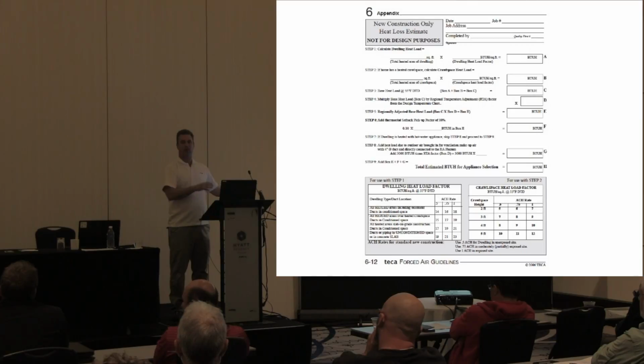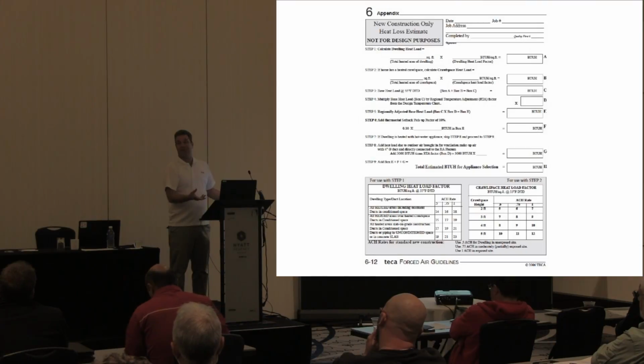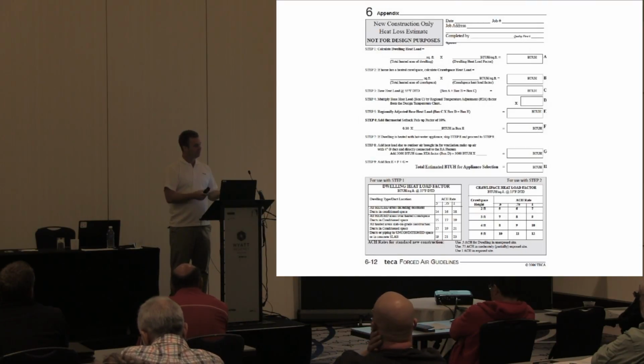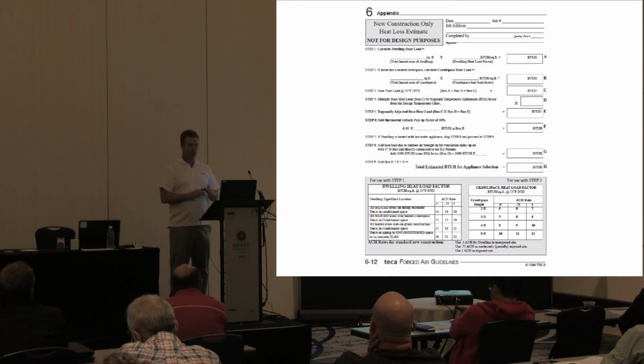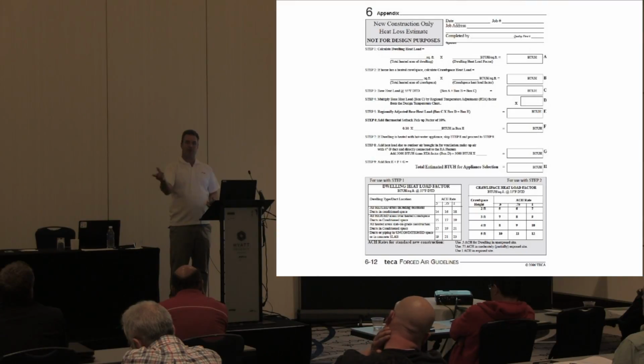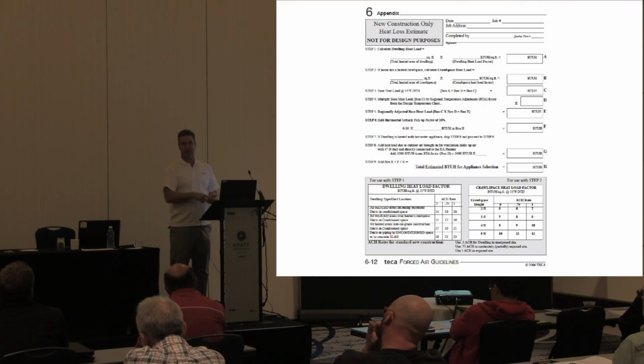The whole basement, or the whole lower floor, will probably be left roughly the same. The back side of the main floor will probably not be that far off, maybe even the lower floor. But that big room with all those windows and the view and the sun shining in, you're going to have issues with that room constantly. So you might as well decide from the beginning, hey, we were going to put this furnace in, maybe that furnace now gets downsized a little bit. Even if the duct is already in, you cap off all those vents and put another system in for that one room to counteract. Or leave a couple of vents in for air movement and just supplement it with something else.